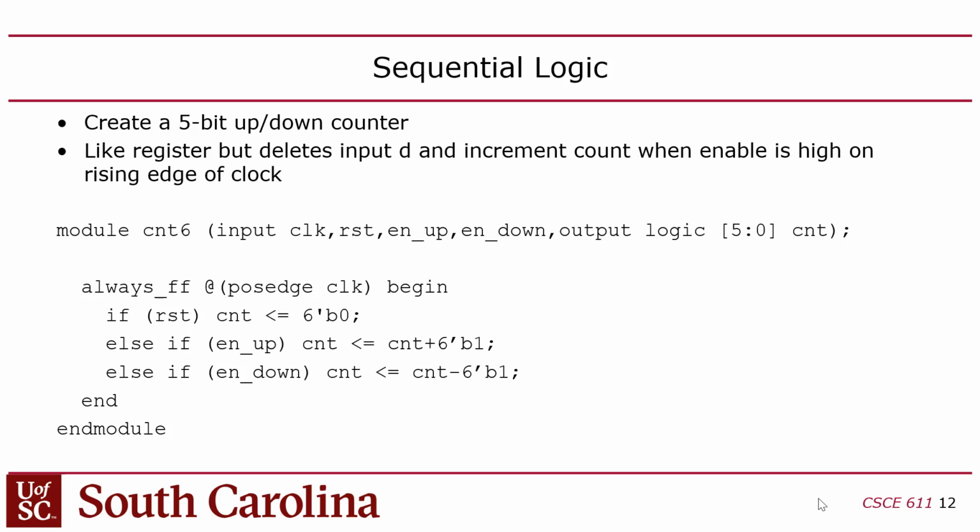Okay, so you can think of it like the program counter creates a 1 cycle delay, and then the program RAM or ROM is going to add another cycle of delay. Make sense? So it's going to take a cycle to increment the program counter and another cycle to read whatever was addressed by the previous value of the program counter.